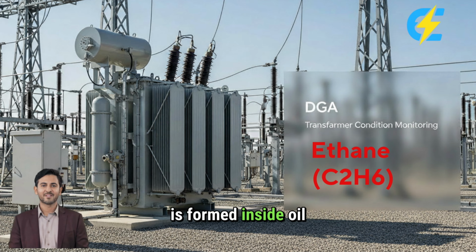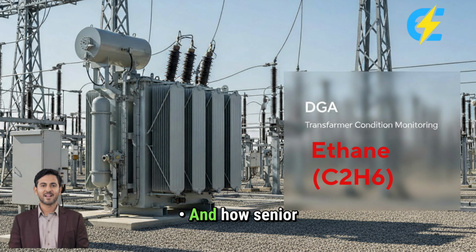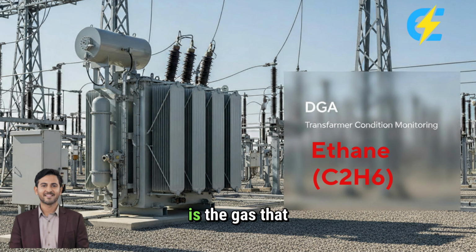Why ethane is formed inside oil. What temperature range it represents. Difference between methane versus ethane behavior. Why ethane is a warning before ethylene. How ethane trends predict future overheating. And how senior engineers use ethane to act early. Stay till the end, because ethane is the gas that tells you still have time, but not much.